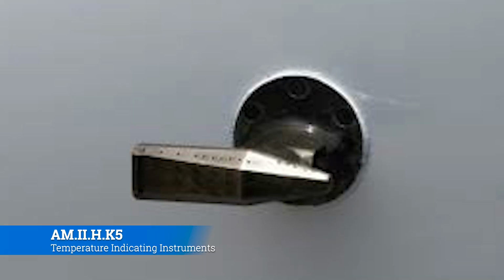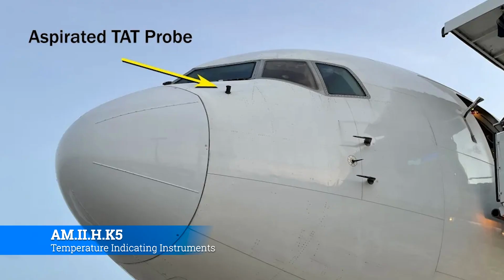Another specialty air temperature system is a TAT, or total air temperature measurement. What that will do is tell the airplane, hey, this is what the air temperature is outside, but then it takes into account the speed of the airplane, because the speed, as it goes through the air, will change the temperature reading. It's either going to get really cold or really hot depending on what speed it's at. So that has to be taken into account, and a TAT gauge will do that.